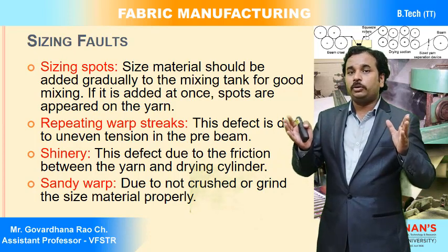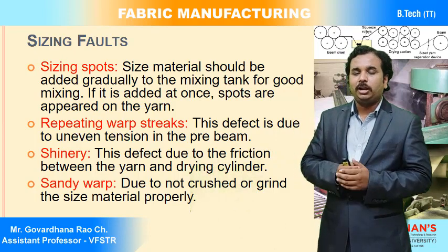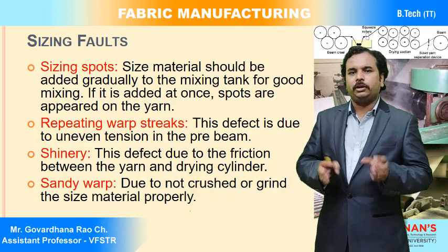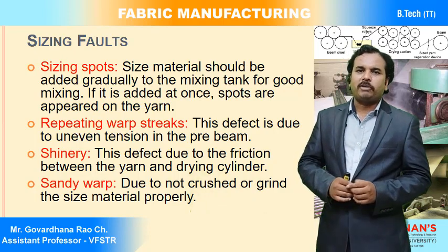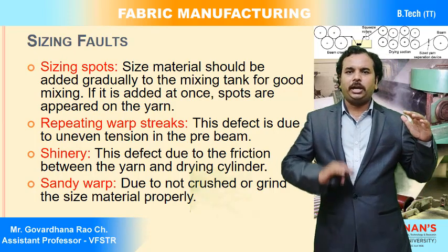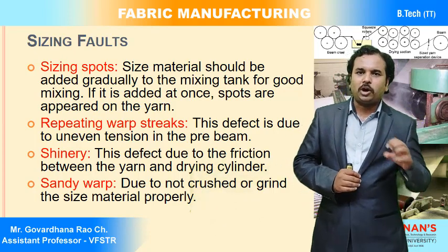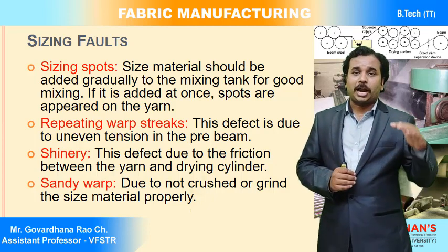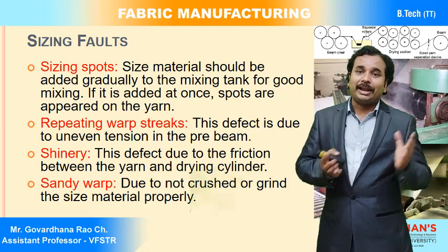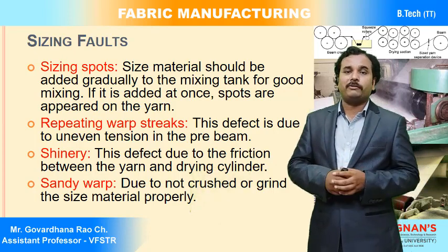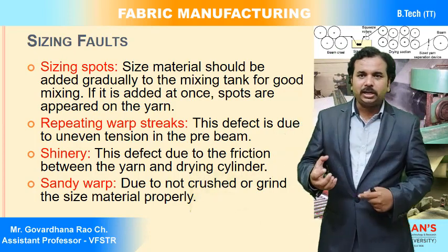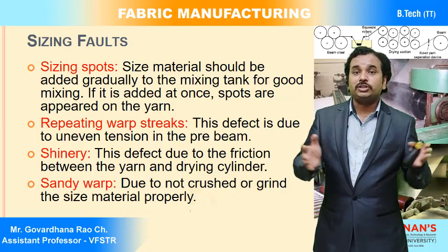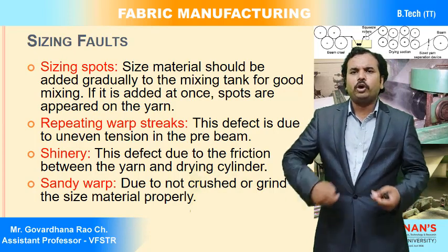If you do not maintain the size paste level, and wait until the size paste in the size box is completely exhausted, then what will happen? From the starting to the ending of the size paste, the add-on into the sized warp sheet is going to be different. At the starting time the viscosity is different, and at the ending time of the paste the maximum amount of water content is going to be added into the warp sheet.